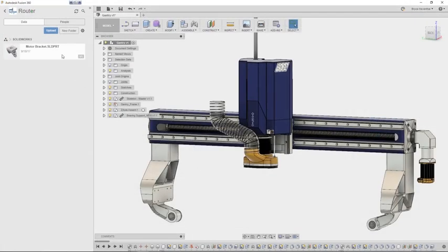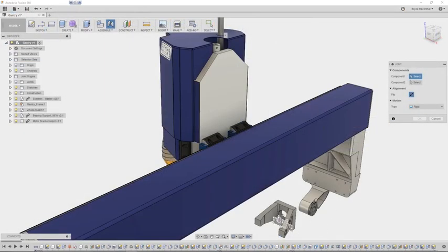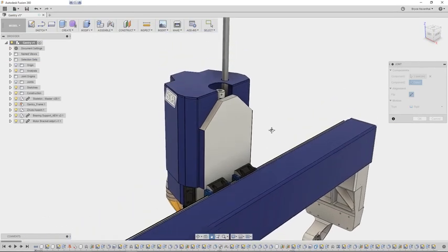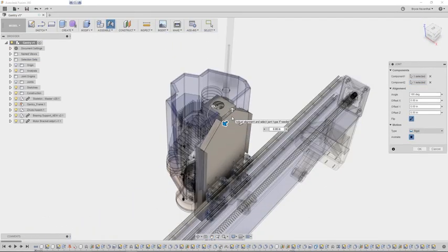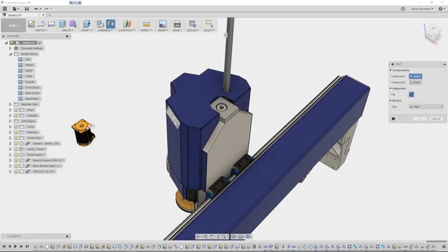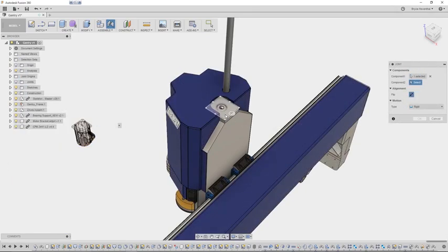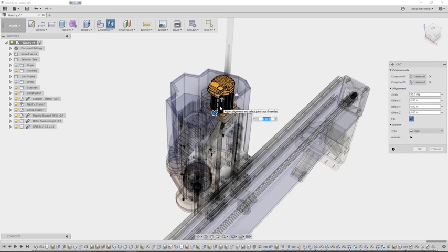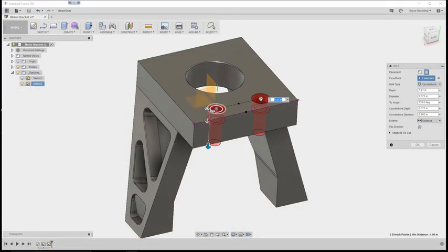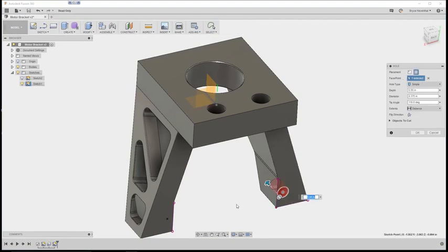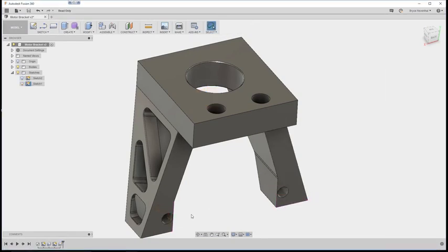Once in Fusion 360, we can insert that native SOLIDWORKS file into our Fusion 360 design. Now we can assemble the design from our contractor into our assembly to ensure the form, fit, and function works with our CAD data. But integrating that design into my assembly is just the beginning. Now that we know how the bracket is mounted, we can add other features to this native SOLIDWORKS data, which will update parametrically in time with any design changes from SOLIDWORKS.